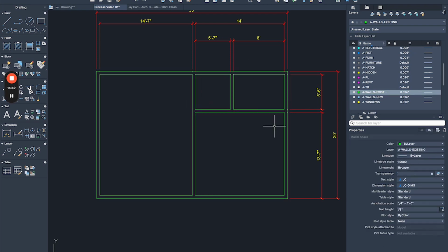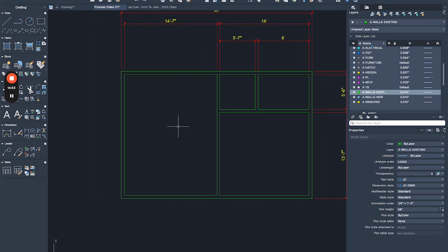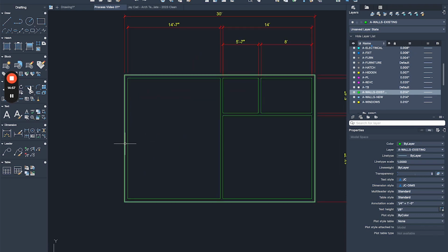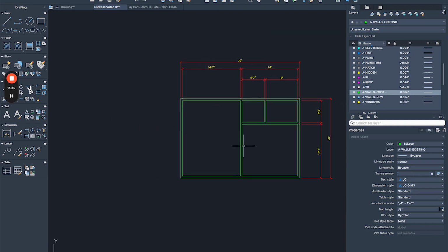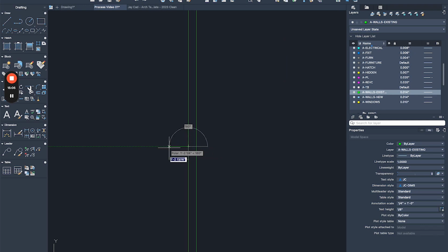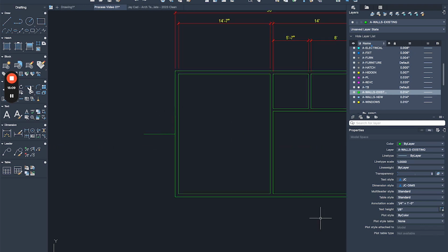So I like how things are looking right now. And then now I'm going to proceed to adding the openings. Now, to add the openings, I like to make the entry a little more special. So in this case, I'm going to do like an extrusion here, maybe a 5 foot. So I'll actually reference the middle point from here. In case you're wondering how to reference the middle point, it's because of the drafting settings that I have active here on the bottom. You want to make sure object snap is active.